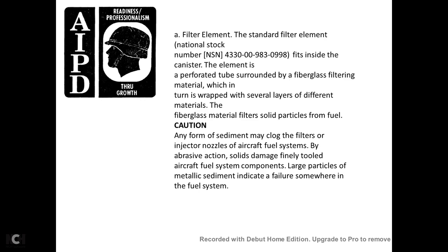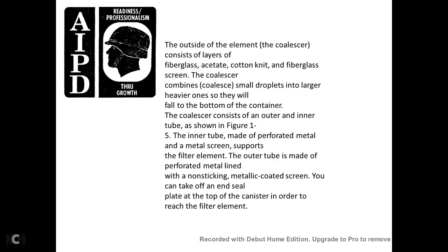Caution: any form of sediment may clog the filters and injector nozzles, and damage aircraft fuel systems by abrasive action. Finally, it may damage tooled aircraft fuel system components. Large particles of metallic sediment can cause failure somewhere in the fuel system. The outside element of the coalescer contains layers of fiberglass, acetate, and fiberglass screen.